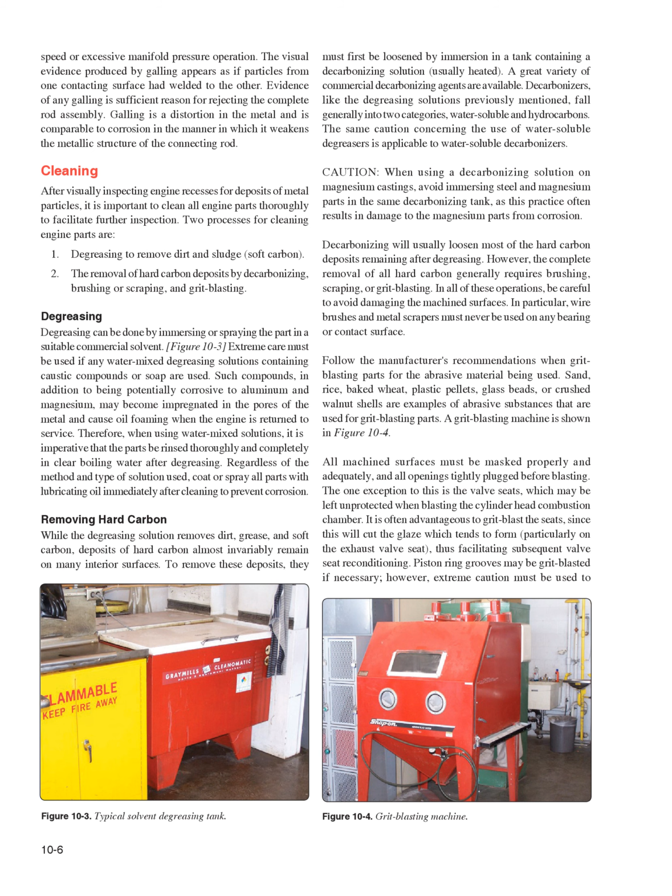Cleaning. After visually inspecting engine recesses for deposits of metal particles, it is important to clean all engine parts thoroughly to facilitate further inspection. Two processes for cleaning engine parts are: 1. Degreasing to remove dirt and sludge, soft carbon. 2. The removal of hard carbon deposits by decarbonizing, brushing or scraping, and grit blasting. Degreasing can be done by immersing or spraying the part in a suitable commercial solvent. Figure 10.3.